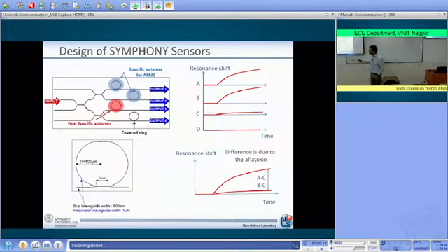And this is the circuit that we are using. Here we have an input waveguide. Here we have a splitter, so a fraction of the power is sent to this arm here, a fraction is sent there. Then here we have another splitter, and so 50% is going there, 50% is going there. Here we have another splitter, 50% is going there, 50% is going there. So we enter from here, and we are able to send the same amount of signal on all those 4 different microring resonators. So we excite all the microring resonators at the same time, and therefore here we have 4 different outputs. Output 1, 2, 3, 4.